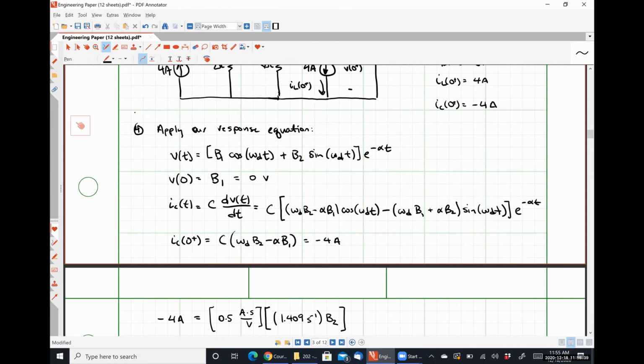It is very, very important that your first equation comes from the normal function and your second equation comes from the derivative. So if we had tried to determine the inductor current, it would have been our first equation and the inductor voltage would have been the second, because the inductor voltage has the derivative-based relationship.